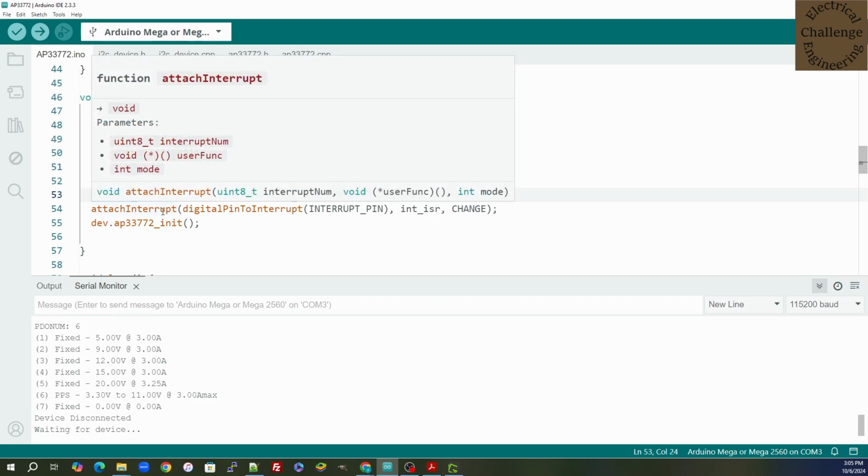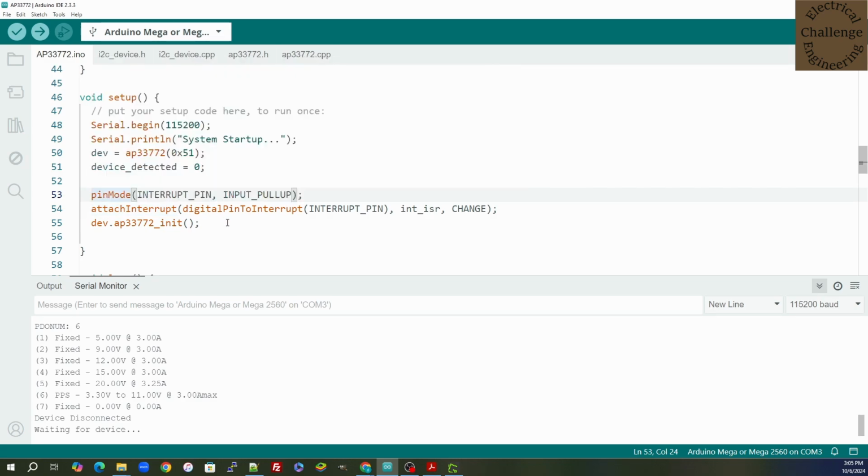The controller also has some interrupts. The chip has some outputs, some interrupts, so I went ahead and attached an interrupt there. I'm not using them for this, but it's things like over temperature faults, over current faults, over voltage faults, anything that causes the chip to go into a frenzy, it'll send an interrupt, and then I can get some feedback over the I2C lines.